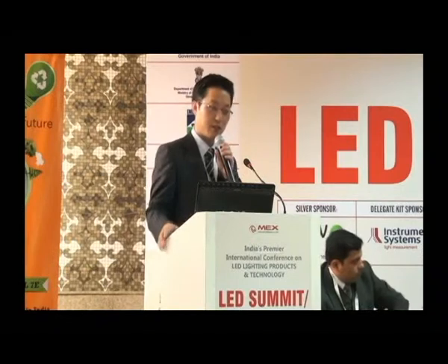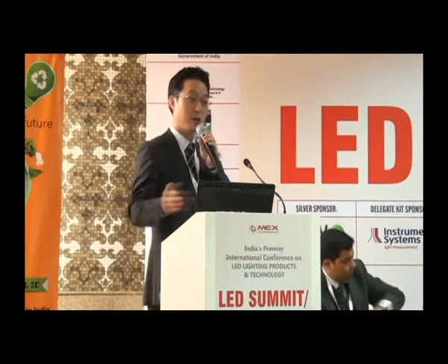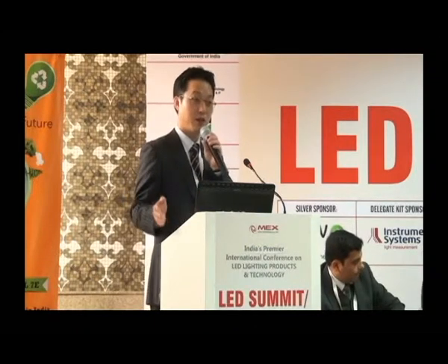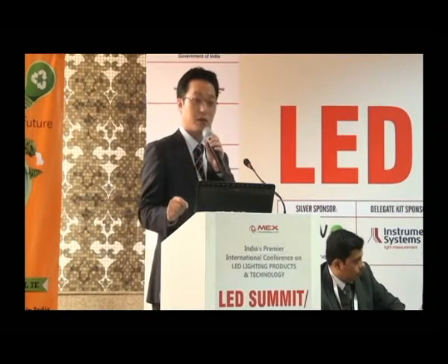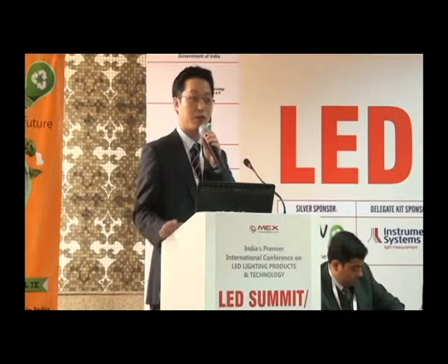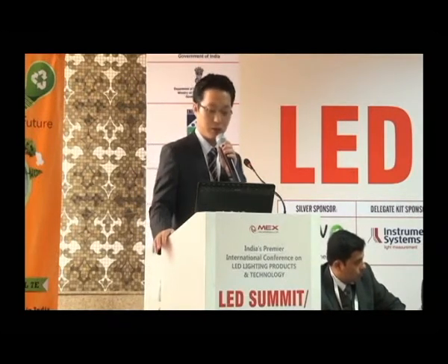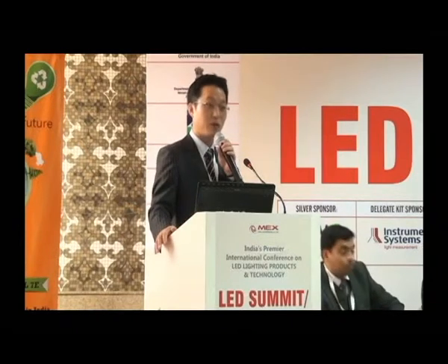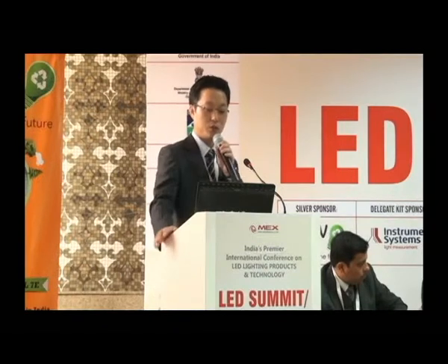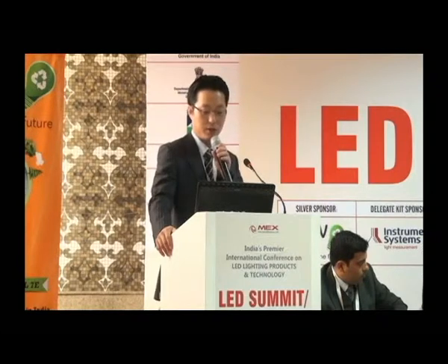So in this case, they just coat white silicone on the printed circuit board, the PCB, and then put the LED chip on top of the PCB, do the gold wiring and encapsulation, and that's all. With this kind of new material, you can decrease 3 or 4 steps to make LED lighting. So I think it will be the next generation LED lighting structure in the future.